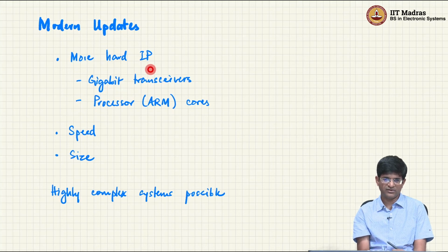Soft IPs are ones where you are given the design in a form like Verilog code, and then you can go through, synthesize it and put it onto your FPGA wherever it fits. Whereas hard IPs already have taken up some space on the FPGA, but as long as you need that IP functionality, they are extremely efficient implementations of what needs to be done.